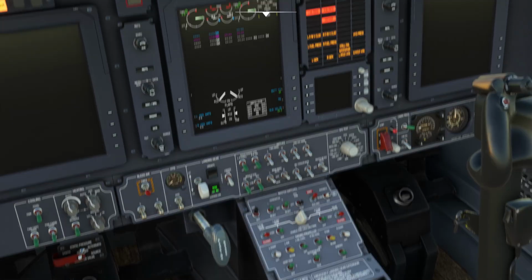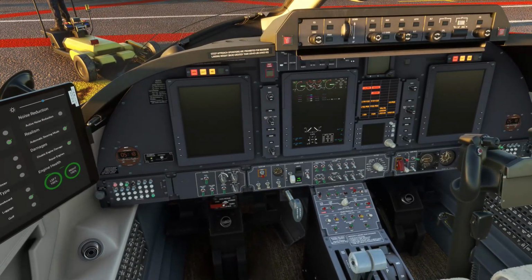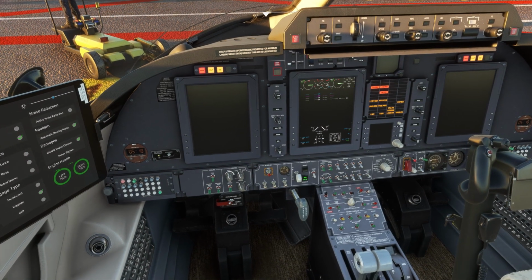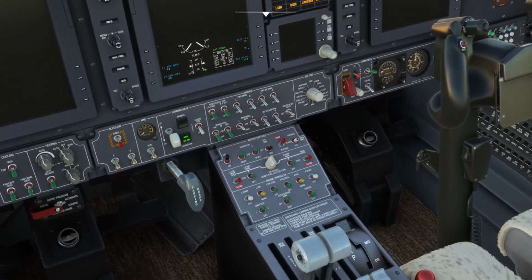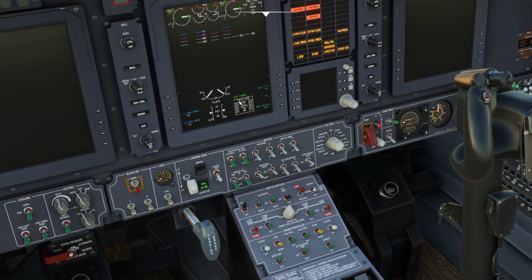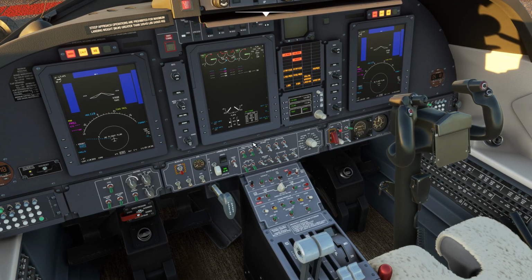So generally, depending on your options, if you have GPU, you will switch it differently. If you don't, you will switch it differently. So let's get our GPU plugged. So our GPU is plugged, and then you have on MFD external power message here. So we can get our avionics all the way to avionics, and that brings all the systems here.